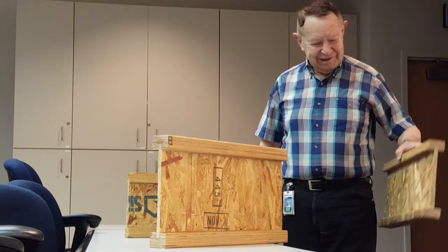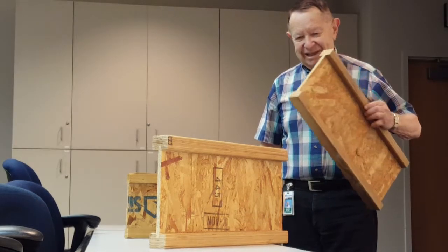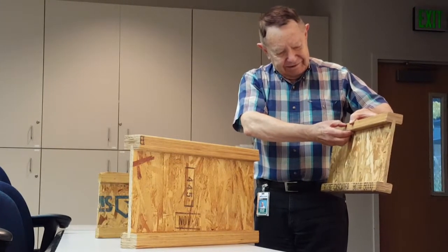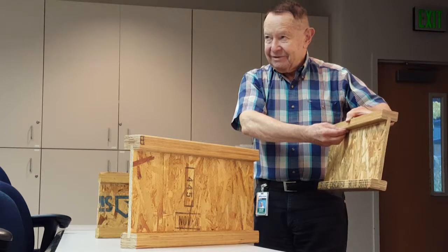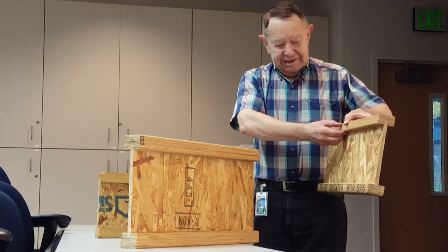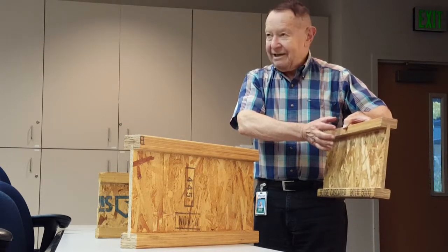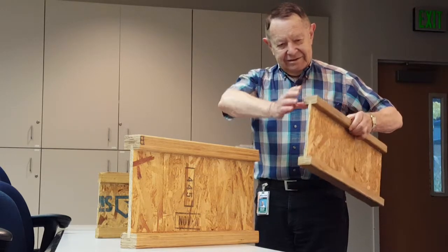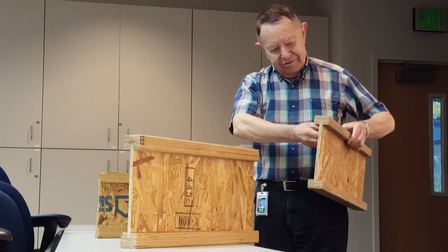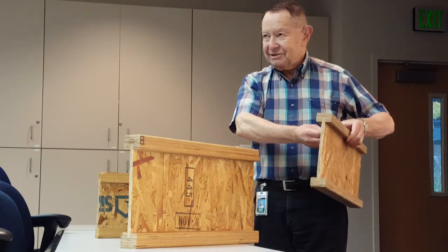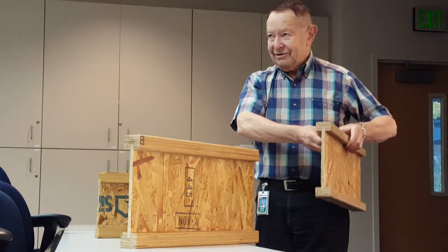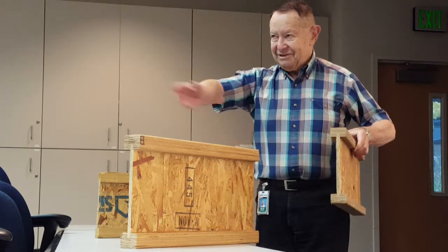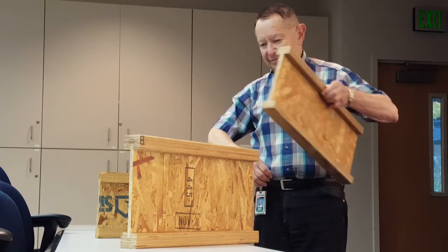They used to burn this, but this is what you get now. And these, if you look closely, are laminated. They're thin strips laminated together. You call this laminated veneer lumber, LVL. And the glue that's binding these strips together is stronger than the natural wood would be from the tree if you just cut it as dimension lumber.